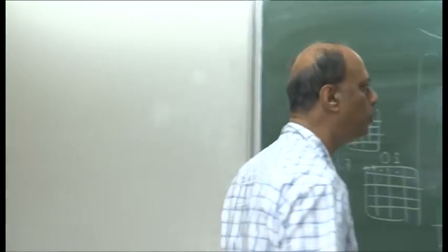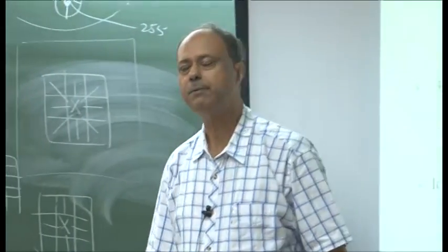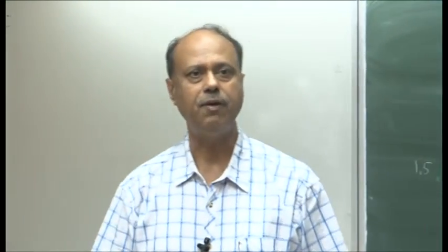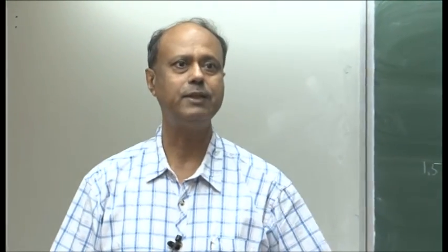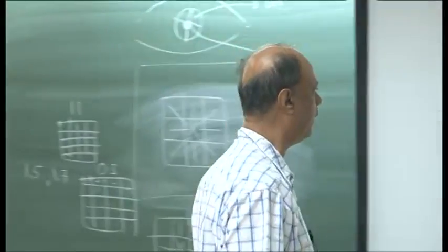Now while you are doing these operations, you must ensure that the value must be less than 255. If it is more than 255, you are in trouble. Then it will take some negative value because of overflow, right? So you have to ensure this part.